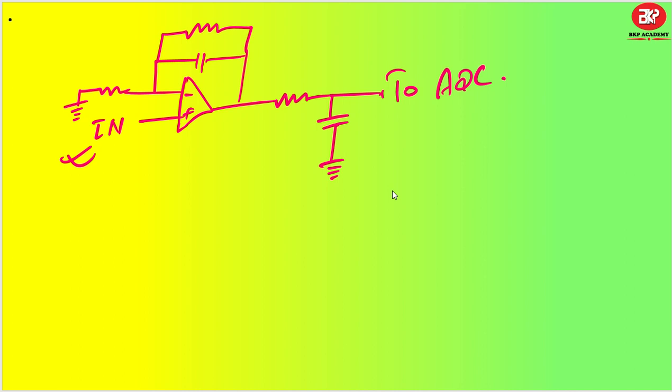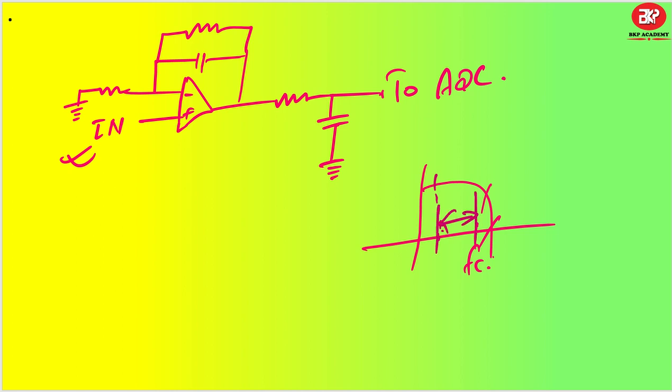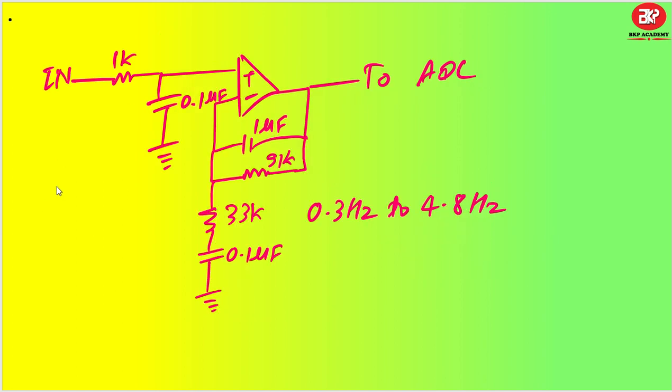Now there are various occasions in the medical field or elsewhere where you do not want just the low pass filter, okay. Let's say this is my FC; you want something which will cut off the lower frequencies also. You don't want signal below this. So let us say we want this much, okay. For that you have to have a band pass filter. These band pass filters are basically used in heart rate monitoring. Let us say we have some signal coming from the heart rate outputs, and we have to send it to the ADC to understand my heartbeat, okay.